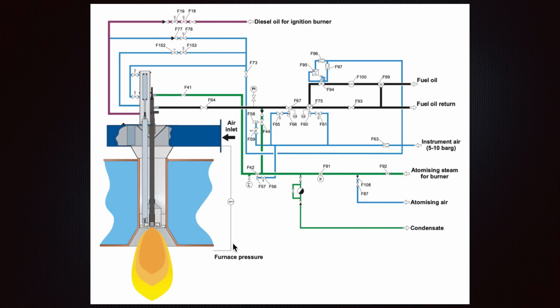that's why if your reading is wrong, your boiler will still operate, but in different ranges. It will work, but it will not give a proper indication of what is going on, and then some problems can start with the burning process.